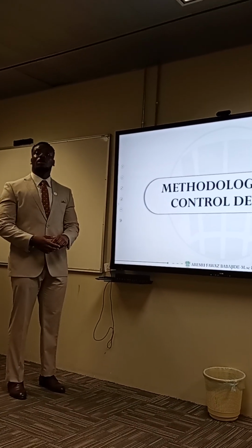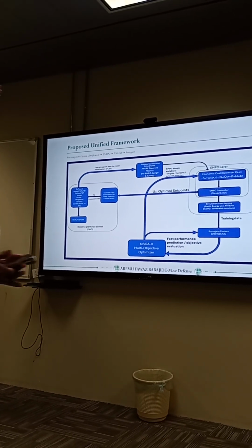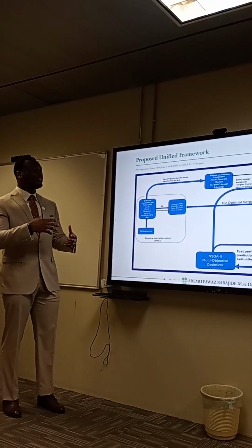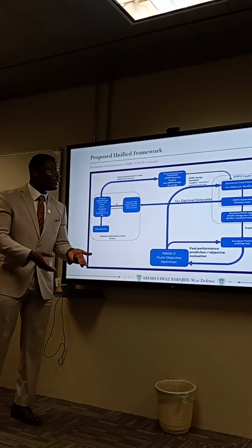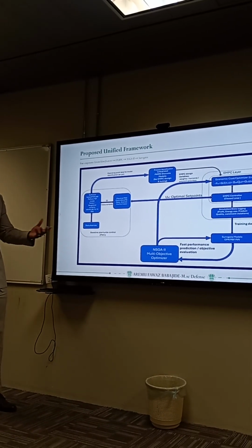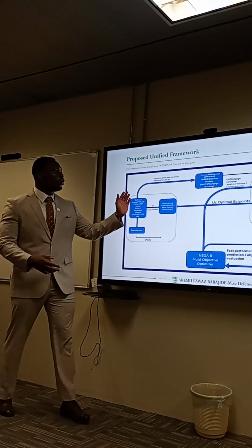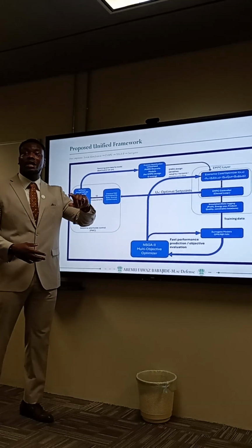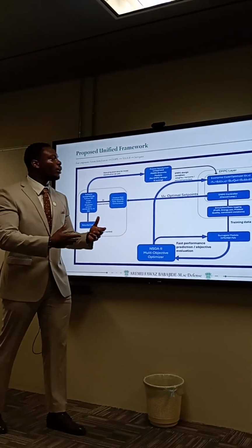And basically, we'll look into the methodology. Just to simplify things, we developed this block diagram that synergizes a unified architecture that integrates not just regulatory control, but also optimization as well as multi-objective goals. From the block diagram, you can see we have the baseline plant-wide control, and then we try to get a model. Now, we are using a NARX model. We'll get to that in a second. Even though the topic says mechanistic, we'll get to why mechanistic didn't work out in the end.